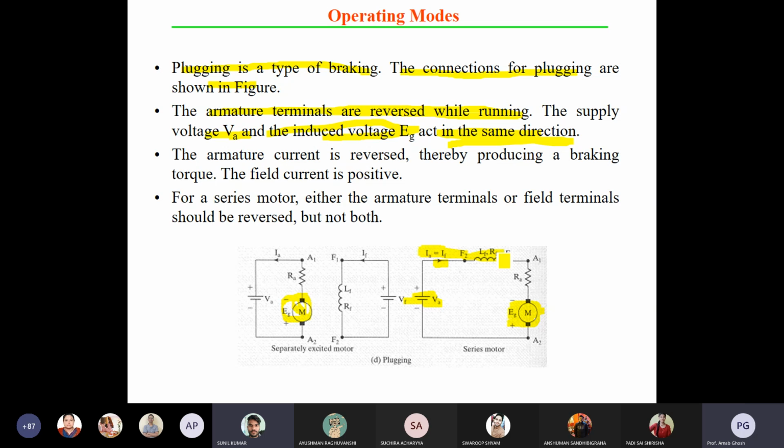There is a cancellation of field. Some of the field points are highly concentrated with magnetic field, and some portions are cancelling each other. So there is an inequilibrium, where one portion is trying to move. The flux density is less in some portions and high in others, so it tries to move from higher density to lower density. That causes the development of the torque, and due to torque your total armature winding is rotating.